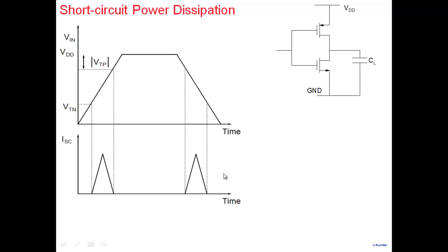So there's a power dissipation because of this. Every time you are switching an input from low to high, you're getting a current flowing from VDD to ground here. And every time you're switching the other way, a current is flowing here. So normally we model this as power dissipation. As I said, it's a triangle. So if the peak value of the current is I peak, the average value is half of the peak. And this is a fraction of the rise time, tau r. So it's not flowing for the entire rise time, but as I said, this is an approximate expression.